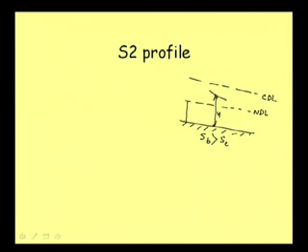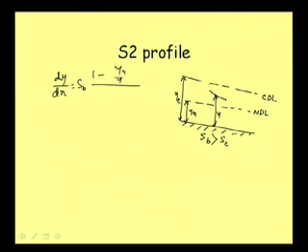now we can all be confirmed about one point, that when a flow profile is occurring in zone 2, it will always be a falling profile, because from this equation it is very clear. And now whenever we get a flow profile in zone 2, we can draw it as a drawdown profile, because of this equation dy/dx is equal to SB (1 minus (yn/y)^3) over (1 minus (yc/y)^3).